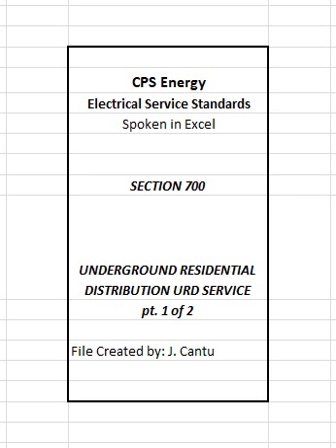B. Call before digging. Texas law requires anyone, including homeowners, who plan to excavate to notify 1-800-DIG-TESS or 811 for location of underground facilities at least 2 working days in advance so that the utility lines can be located and marked for safety. Helpful numbers are listed on the inside front cover page.